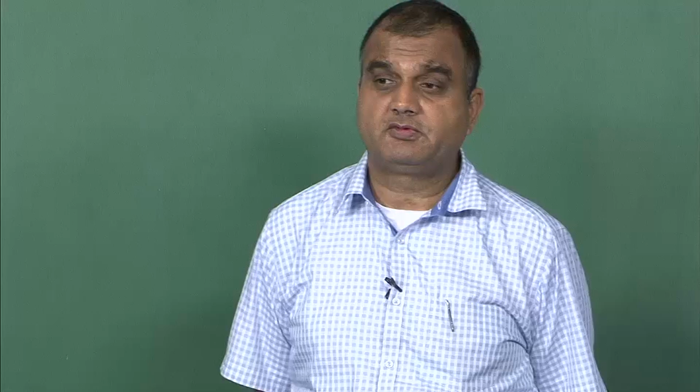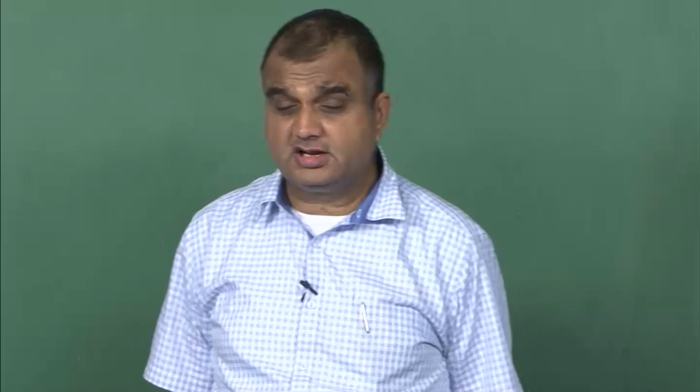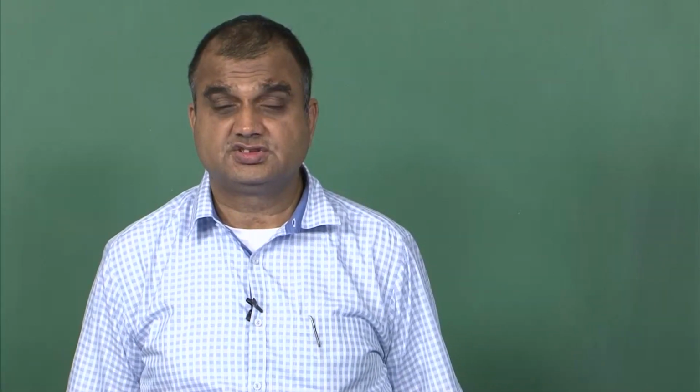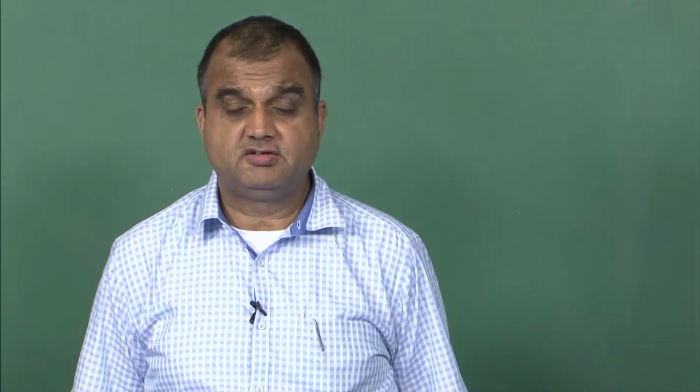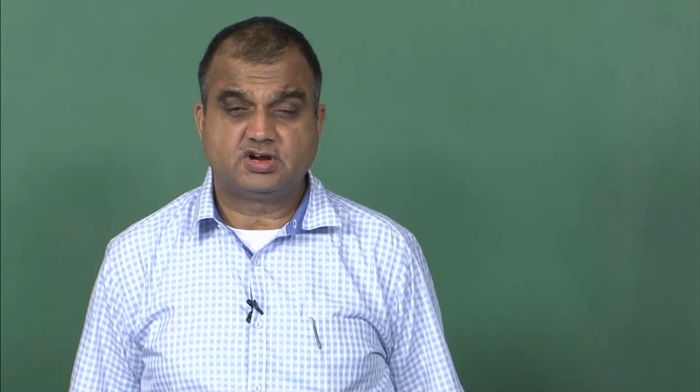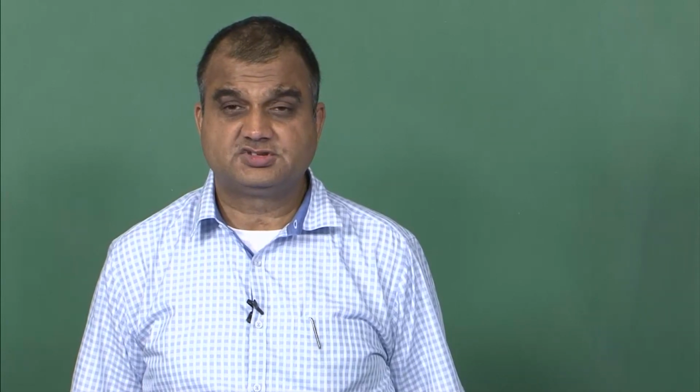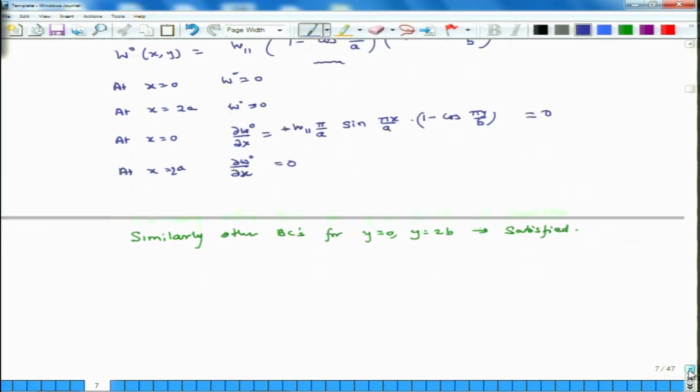We do not care whether the function satisfies the governing differential equation or not, and we also do not care if there were some boundary conditions not related to u, v and w and derivatives of w, that is, if these boundary conditions were involving n's, m's or nxy, mxy, then the relation for w need not satisfy those also. So, all the kinematic boundary conditions are satisfied.